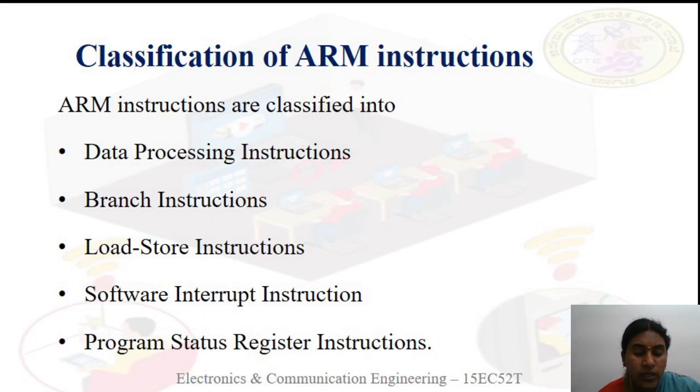So we don't have any instruction to fetch the data found in CPSR or SPSR directly. For that we are going to use the program status register instructions to fetch the data from the register and move the data into the CPSR or SPSR. The program status register instructions are mainly MRS and MSR.